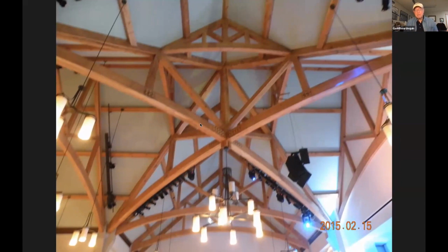So that's a horrendous reduction. And so to get around that, maybe in some cases you could have an isolated strap at the bottom and another isolated strap at the top. That way the straps could float as the wood shrinks. But if you have one solid plate with two rows of bolts, then that's a no-no in green timber.